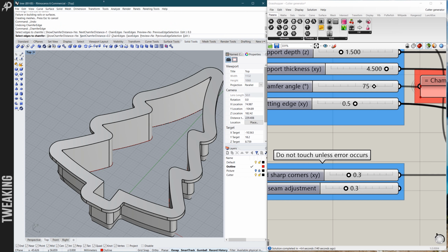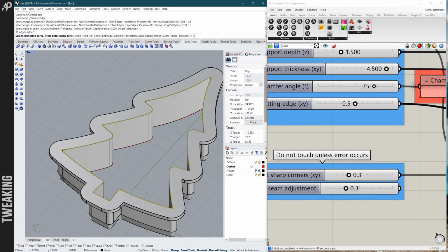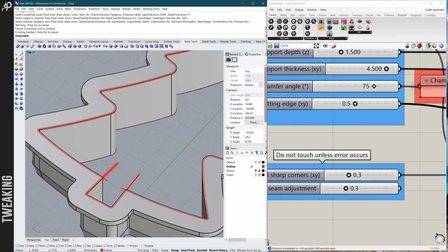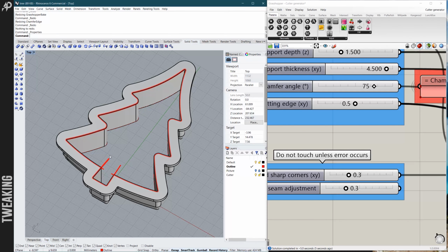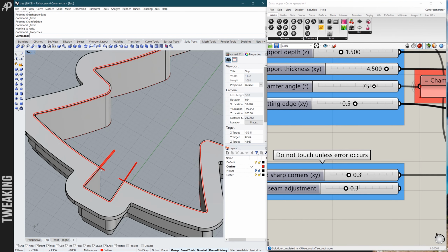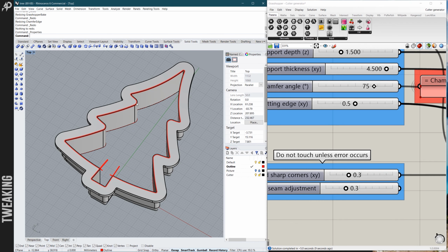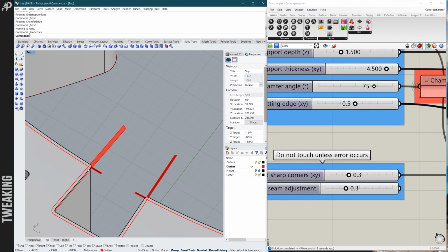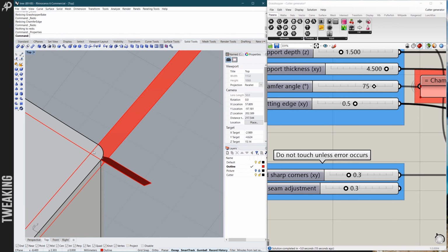So I just type 0.3, C for chain edges, I select, enter, enter, enter, and it broke up. And I know where this is coming from. The defective geometry gives you a hint that the problem is here, the outer corner.